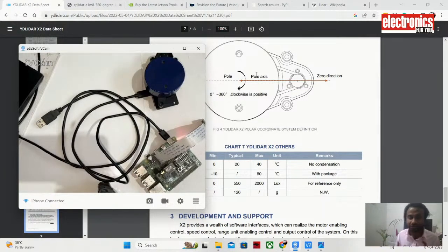So this thing you need to check first: what is your 0 degree angle side of your lidar, and how you can stabilize against the vibration of the vehicle while your lidar is mounted, so that you don't get many wrong data points. So these two things are important.